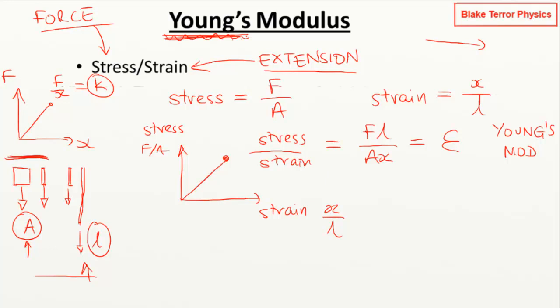So we're going to see similar properties here for Young's modulus as we are for the force constant. If you've got aluminium or some other metal like that, then for a certain amount of pressure, because this is force over area, we're looking at a pressure applied to the material, we're not going to get very much extension, so we're going to get a higher value of Young's modulus in the same way as you get higher force constants.